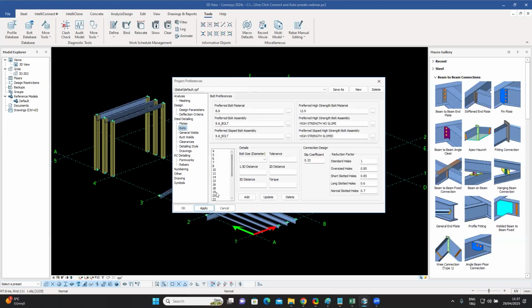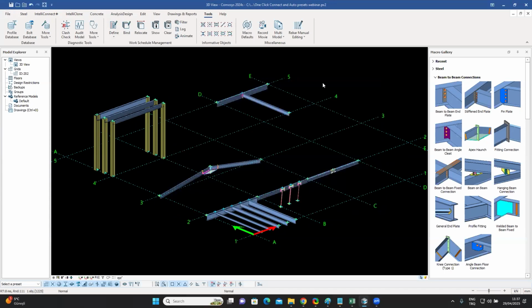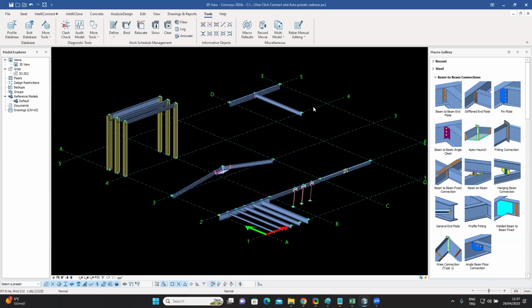If you remember, we talked about the interbolt distances. So what should be the distance between the bolts in the direction of the load? What should be the distance of the bolt to the edge of the plate? You can enter all these for different bolt diameters over here, for example. And this file really helps you understand how this becomes a really important part of the background process.